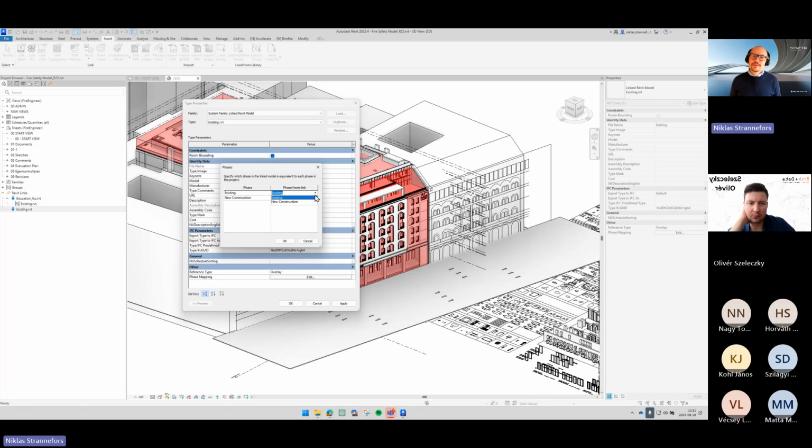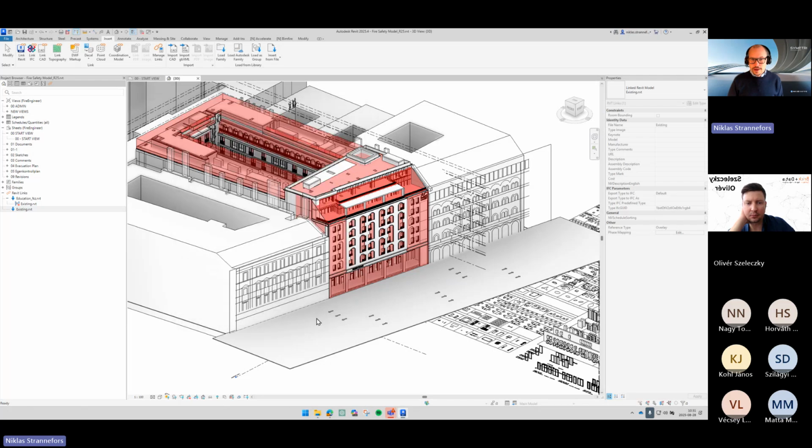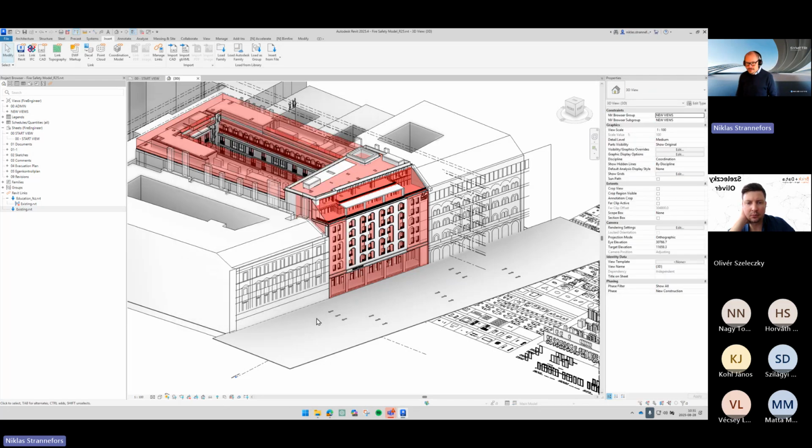As I mentioned in the beginning, this architect and structure model are very forgiving because they're using the standard phase names and they actually have really good phase filters, so it's super easy for us. But I will show this as well, because sadly Revit is not the smartest. What we're using is something called a phase filter.